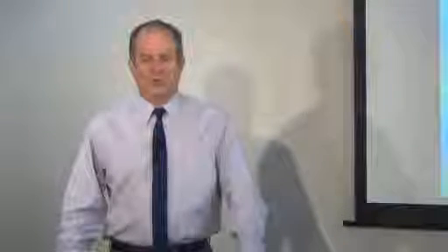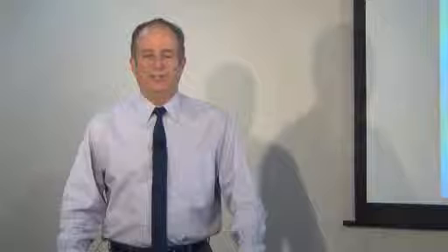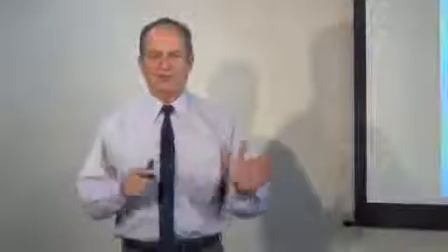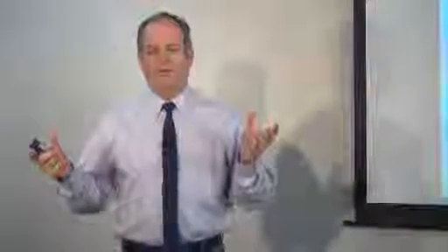Let's summarize what we've learned in Module 4 with the three-phase. We explained voltage and current, phase angle relationships of three-phase loads. Remember how we have the leading and lagging the current, and we're trying to balance that out so we can minimize current and get that current minimal so we have the fewest losses. And actually, if you have a conductor that's good for so many amps, let's say 1,000 amps, like 795 ACSR or something like that is close to that, or 1,200 circular mill type conductor, where it's good for 1,000 amps.